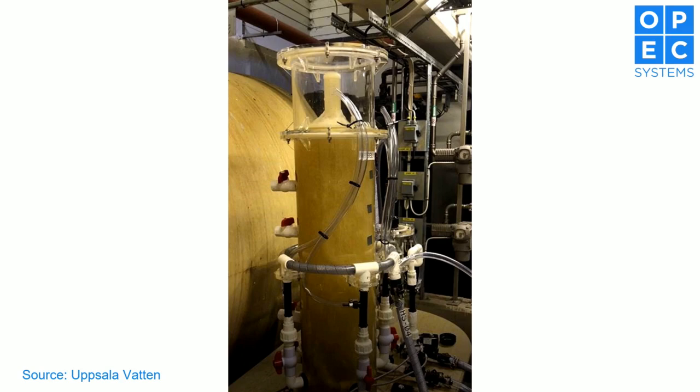And then what have we got on the screen here? Oh, this is a great slide actually. So Uppsala Vatten, which is just north of Stockholm, are a water utility that have currently got one of the bench scale units, and they're treating one of the leachates from one of their landfill sites. So you can see a really heavily contaminated mix of various things that you get out of landfills coming in, and yet the fractionation process is still working really elegantly there. You can see the foam just spilling over the hood at the top.